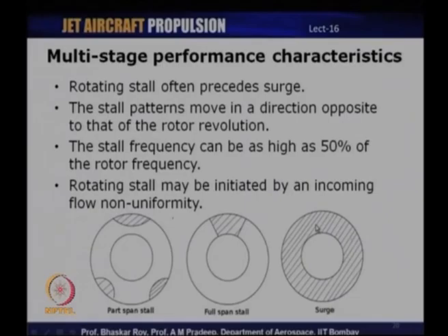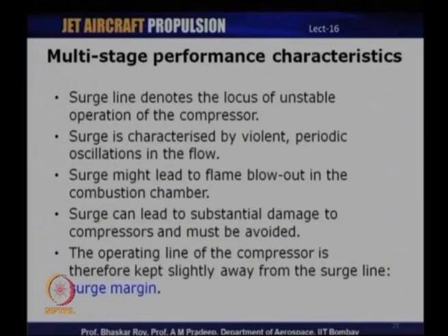So, this means that rotating stall is likely to be one of the precursors of surge. That is, if rotating stall were to continue and progress leading to full annulus stall, it may eventually lead to surge. Which brings us to what is actually meant by surge.